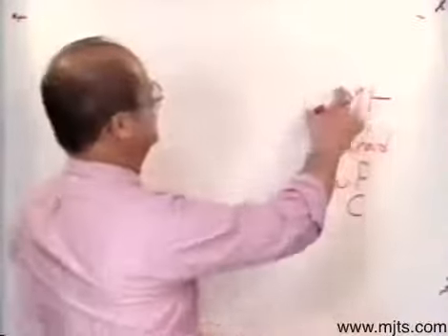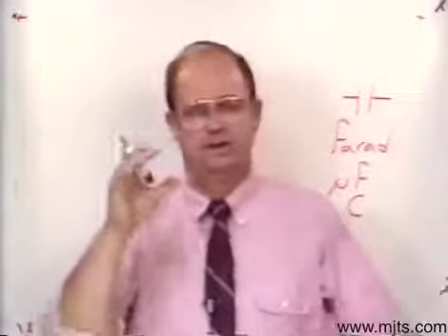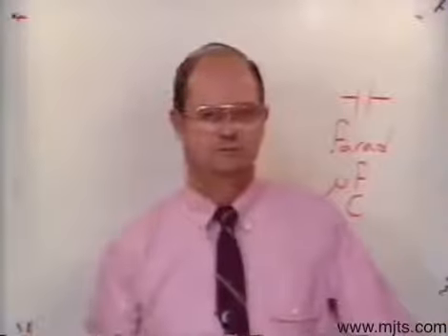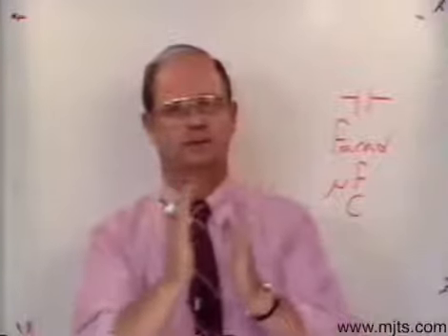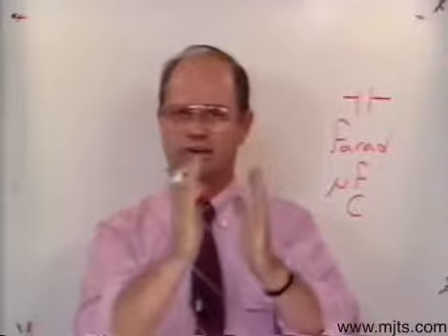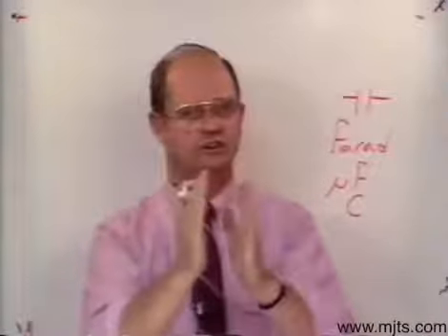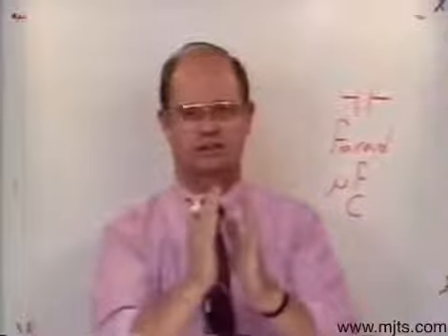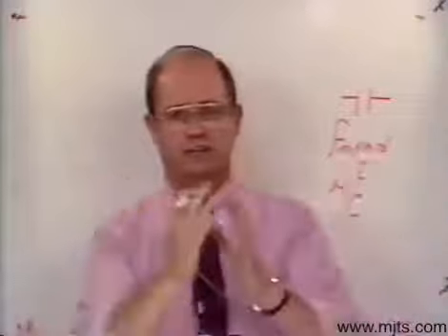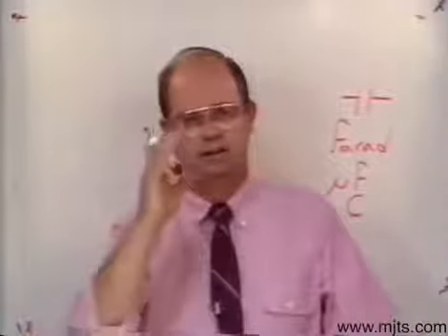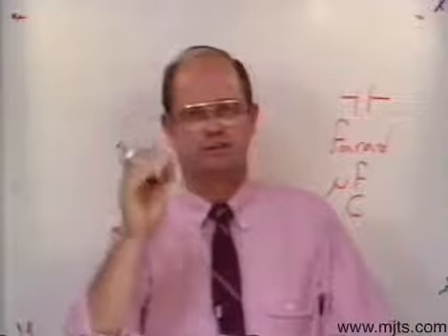Now, we can change the value of that capacitor in any one of 3 ways. We can change the distance between the plates. In other words, the closer they are together, the larger the value of capacitance that I'll have in farads. I can increase the size of the plates. Another one is I can change the dielectric material that's between them.